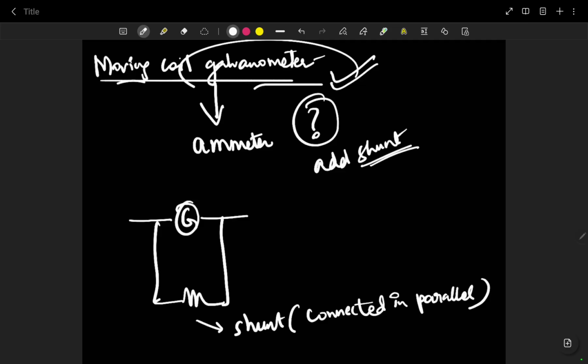So you know that a galvanometer is a sensitive device. It gives full scale deflection for a current of milliamps, right? That is 10 power minus 3. So for measuring currents, a galvanometer has to be connected in series, as it has a large resistance that will change the value of the current in the circuit. So which becomes a difficulty for us, right? To overcome this problem, we will shunt it with a resistor so that most of the current can pass through this shunt. Okay.